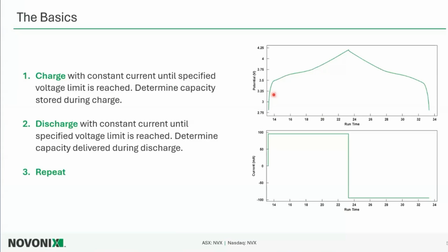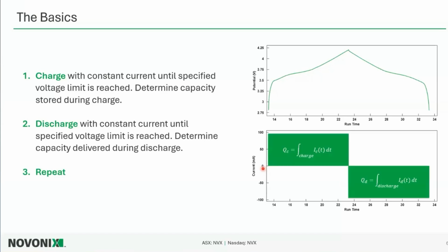So I'm going to start with a brief introduction, picking up where Kevin left off with cell testing. We already talked about galvanostatic testing, so I'm going to actually use that as an example, again, to talk about Coulomb counting this time. Instead of looking at what's happening at our voltage curve, let's look at the information that we can get from actually counting these electrons we're moving through the circuit. So we've talked about this charge and discharge, measuring the voltage response to the current, and how we get some of these cyclometrics by integrating the current over time, like charge and discharge capacity.